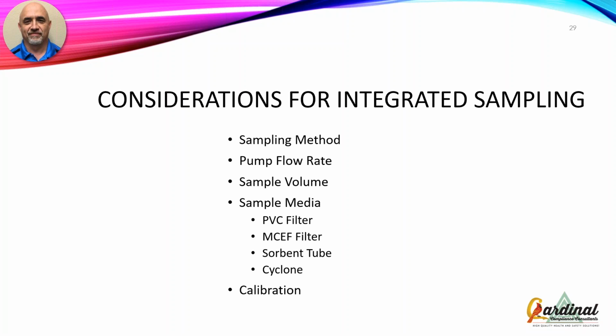So I know this is going to break everybody's heart, but you have to do math. You have to figure that out, because what I've run into, especially for lead, have people do a 30-minute sample on lead, and it'll come back, and you never get zeros with your analytical methods. You always get less than. So the best you're going to do is less than limit of detection. So if my limit of detection is 30, and my data says less than limit of detection, or less than 30, my number's 30. And that's my worst case scenario. But what I've seen, what I've run across before, and particularly with lead, is we have a limit of detection of 70.